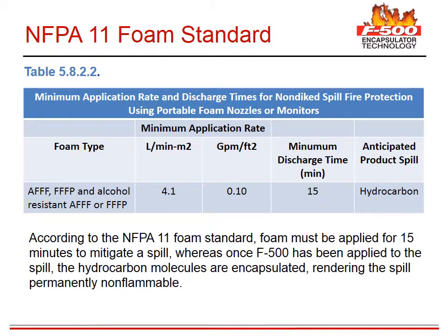The NFPA 11 standard on foam states that in a non-dike spill, such as a spill on a highway, foam must be applied for 15 minutes on hydrocarbons to prevent ignition. F500 is an encapsulator agent and does not work that way. Once F500 has encapsulated the hydrocarbon, it forms a molecular bond that won't break down.